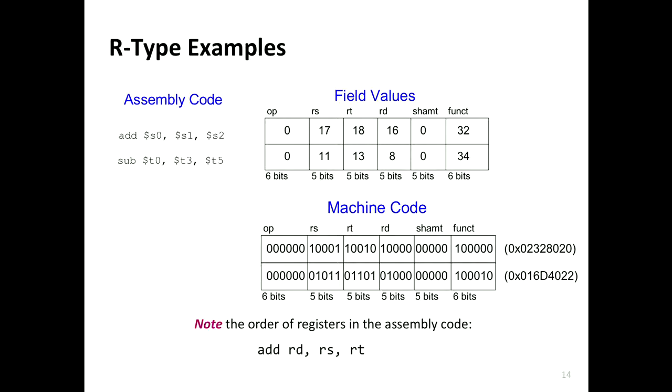Let me go back to this place, and I will say data out underscore RS, because you're going to read your source registers. This will be 32-bit, and the other will also be 32-bit, and you need data out underscore RT, the other source register. Right? What's going to be your input? What data are you going to be writing? The sum of those. But we haven't performed the ALU yet.